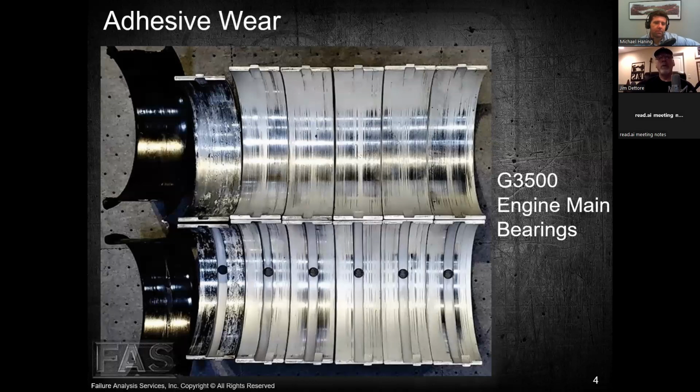So when we start to polish, we're just starting to reach surface melting temperatures. Sometimes that heat is pulled away through conduction into the body of the part, or that heat is pulled away via lubricant films or lubricating oil that's flowing through there. So when we see the polishing, it's an indication of adhesive wear or possibly two-body abrasive wear. Keep in mind that the two-body abrasive wear, if we don't provide a lubricant film relatively quickly, it progresses to adhesive wear like we see here pretty quick. Okay. Are there any questions?